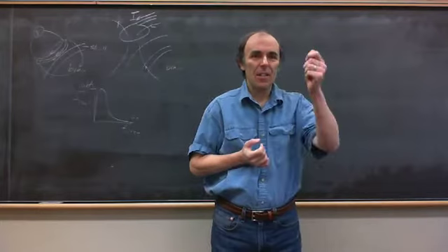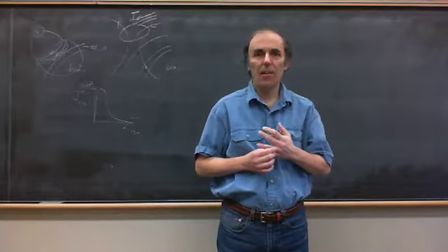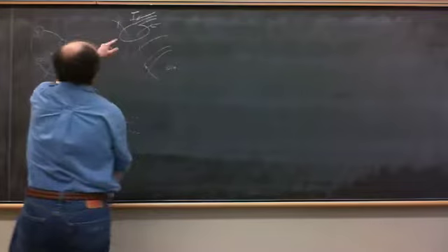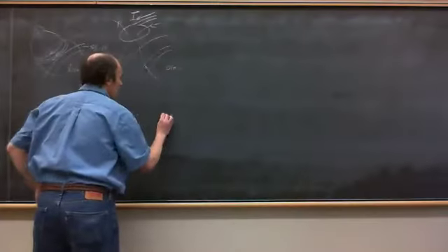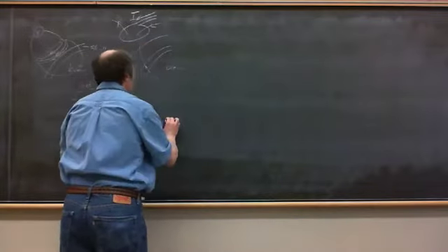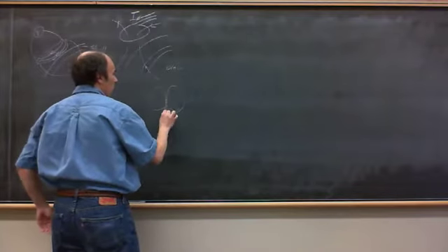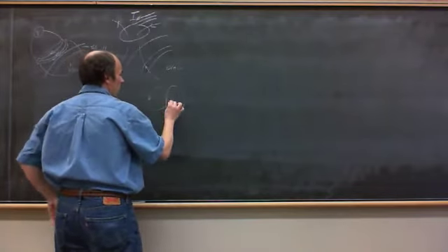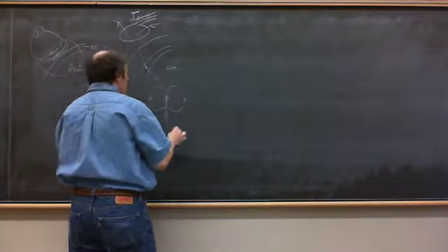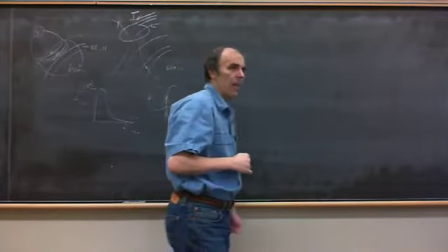You can't get a tenth of a millimeter resolution. Even a millimeter is probably beyond what you can have. But they've designed new coils, instead of a circular coil, a coil that looks like this. Coming up, and then around, and then down. So current comes up in the middle here, and it comes up in the middle there, so it's adding together. You get a large electric field right underneath that part of the coil. That's a figure of 8 coil.